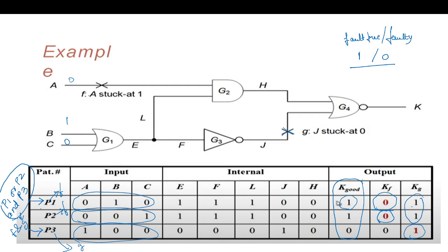So if we consider F fault is there, now this 0 will excite this fault. And what is the value here? 1. So 1 0, fault free is 0, faulty is 1. This is going to be 0. So for 0 0, it will remain 1, and this it will remain 0. So we can see this fault is getting detected.